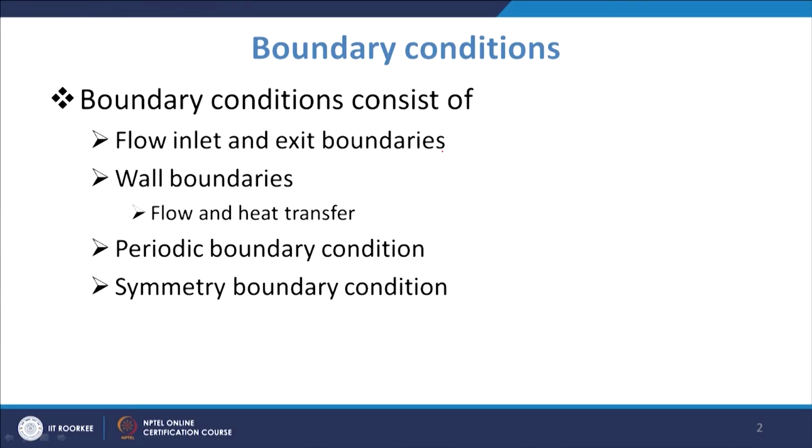Apart from that, the inlet is important, because through the inlet the material goes inside the domain. So, you have to specify the inlet boundary conditions; you may specify the velocity, or you may specify the pressure. Like that you have different ways to represent these inlet boundary conditions. Similarly, you have the exit or outlet boundary condition, where you have the outflow boundary condition or pressure outlet. These are the options available to you, to be applied depending upon the type of problem we are dealing with.